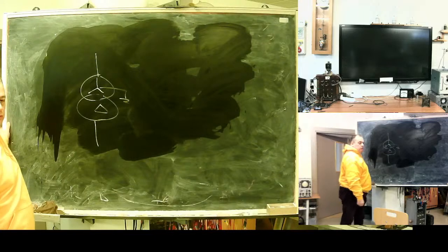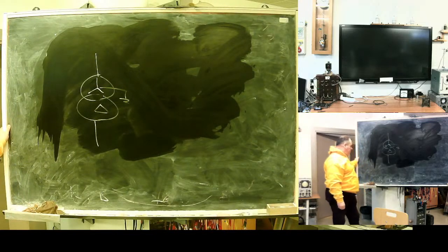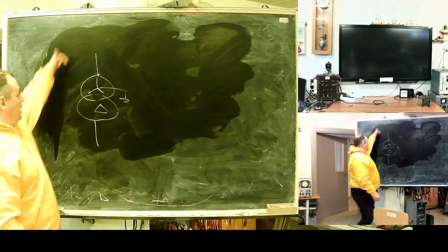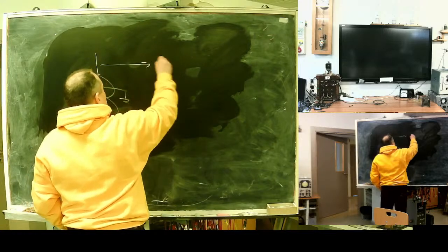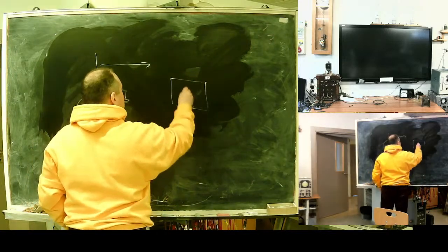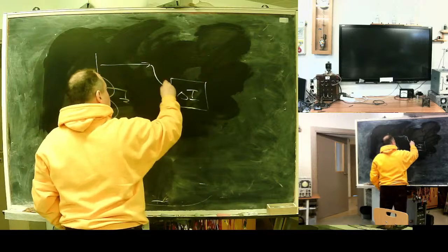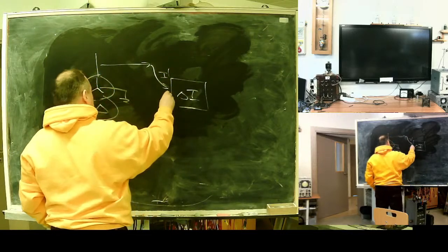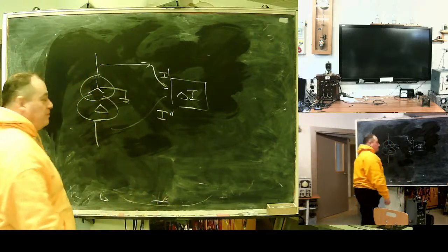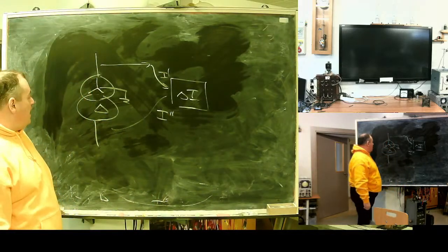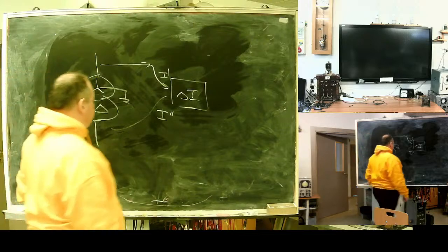You would like to implement protection based on Kirchhoff current law. As in flows, this out flows. So you need delta I, you need primary side current and secondary side current. Yeah, everything fine. Except one problem.